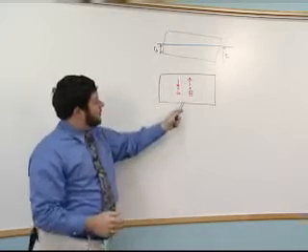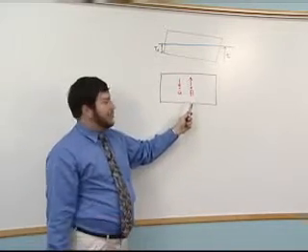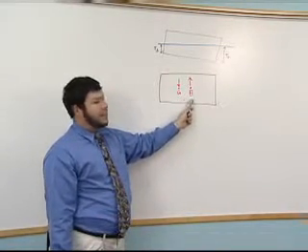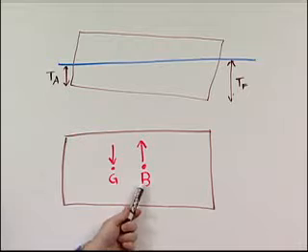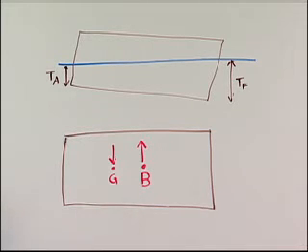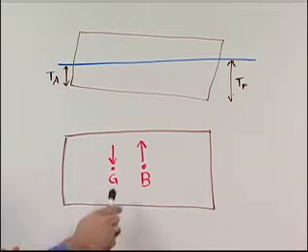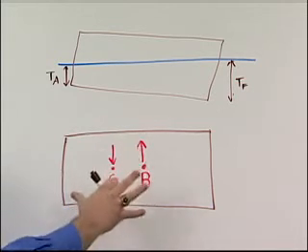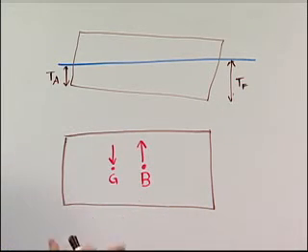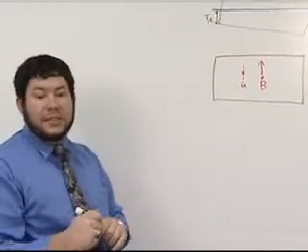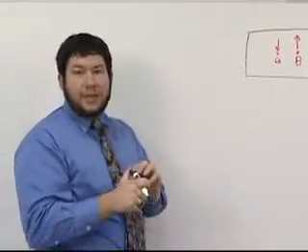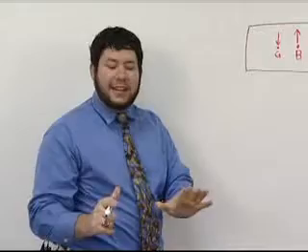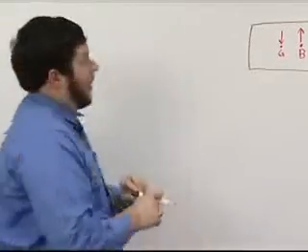And trim is really caused by a difference in the longitudinal centers of buoyancy and gravity. Those two centers, one pushes up and one pushes down, and if they are offset like they are in this drawing, the vessel will tend to rotate until they are in line with each other. Now, to calculate trim, we need to know a few things that we haven't calculated yet, so we'll walk through how to do that now.